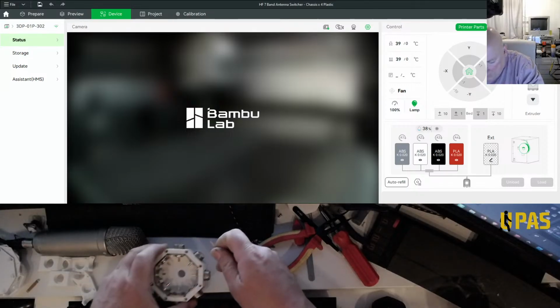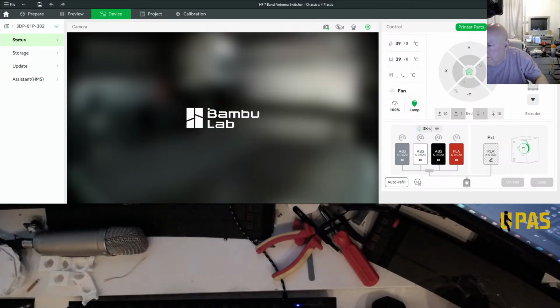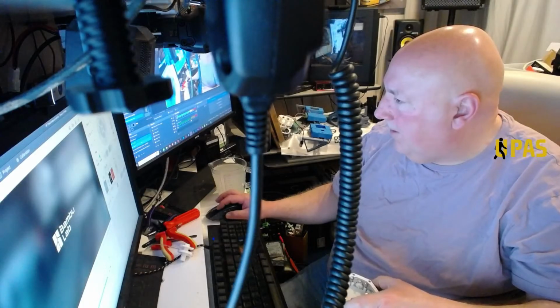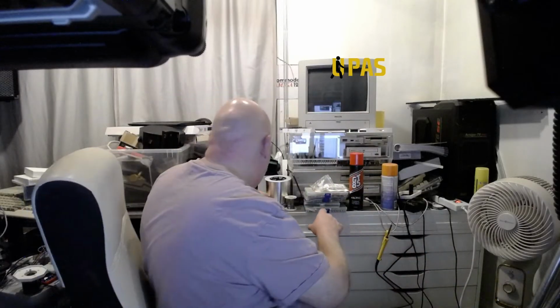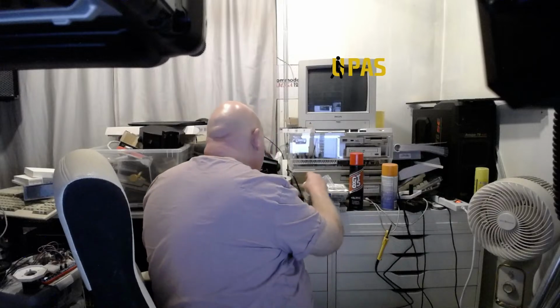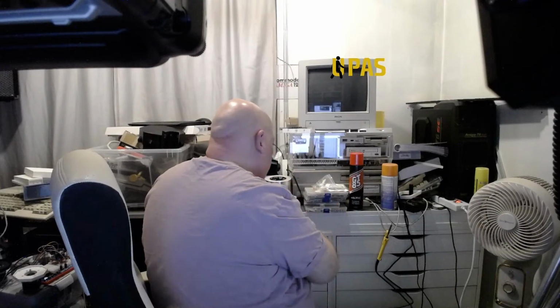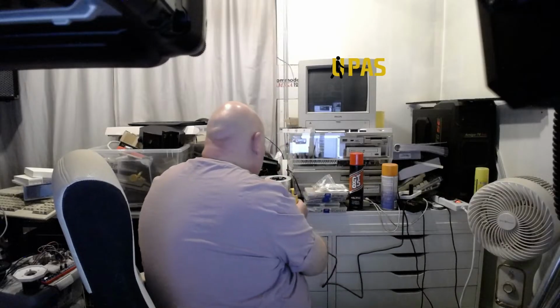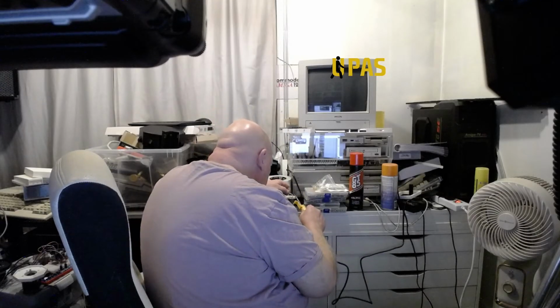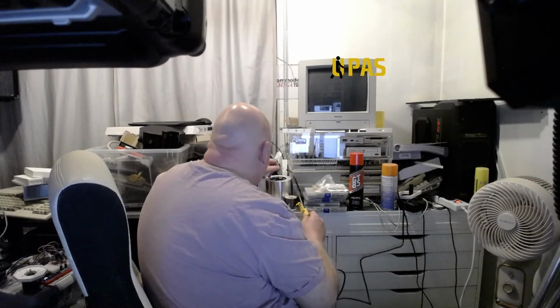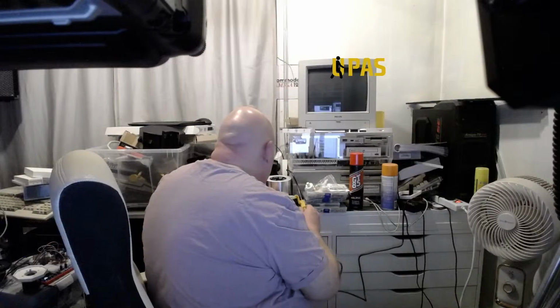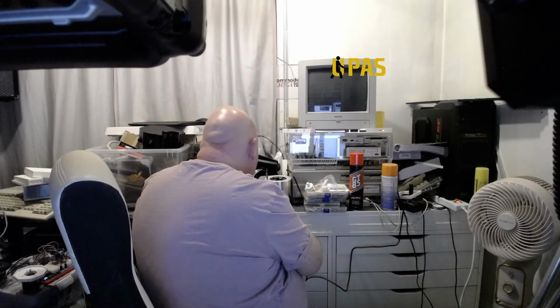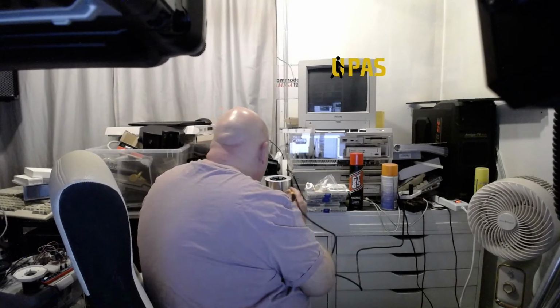Right, I'll try and do it. I've got to take it over here to do it. Okay, let's just take it over here and do it. We're nearly there. So I'm going to tin the end. Tin the end of this. Right. So tin the end. I'm going to tin the SO239 inner.